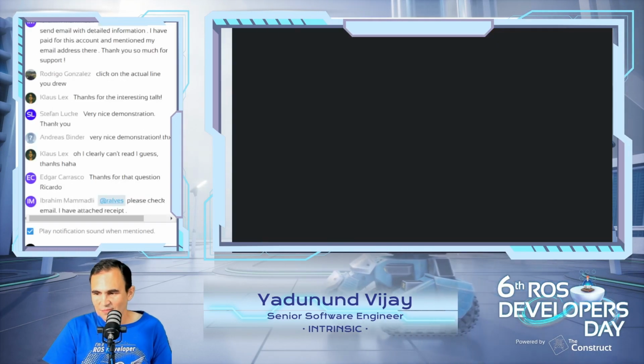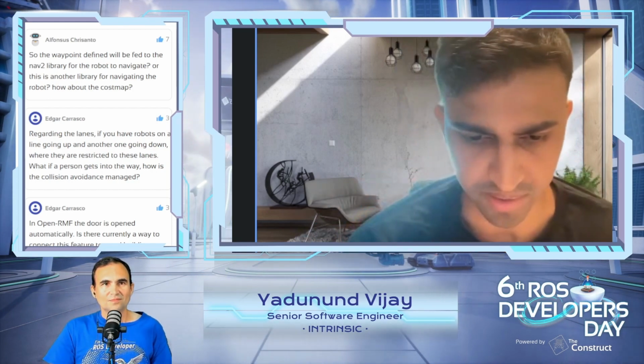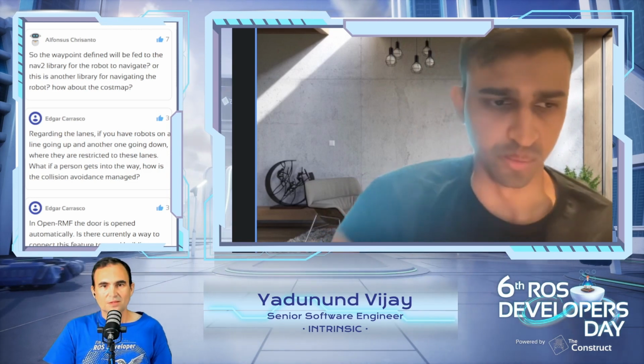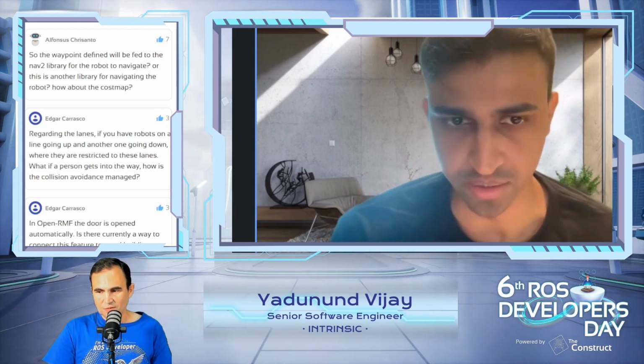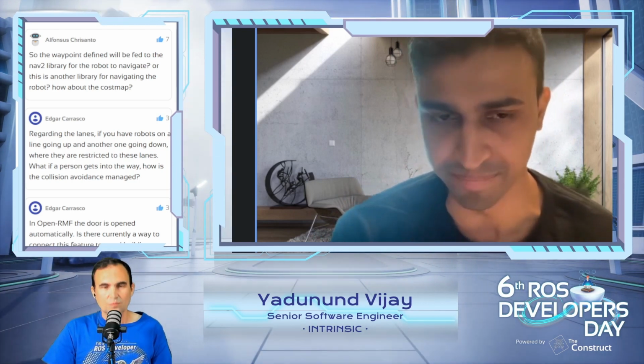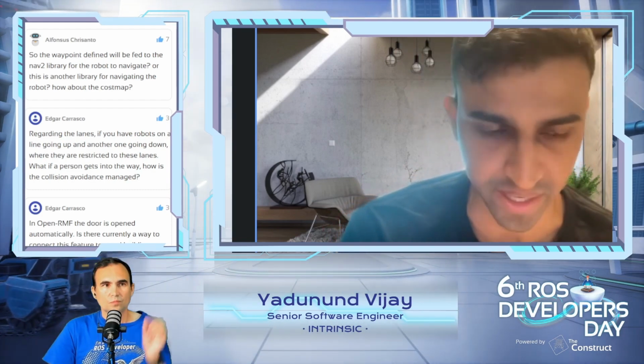Yeah, that's a great question. I didn't have time to emphasize this, but the navigation stack these robots are using in simulation is very simplistic. I think there's a slide somewhere else, but I'll just talk about it. We have our own navigation plugin called Slotcar, and it basically guides our robots in simulation along these straight line paths. It has no sense of the obstacles or the environment around it. It just quickly calculates a trajectory for a robot to move from one waypoint to another.